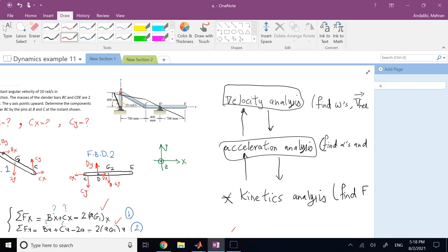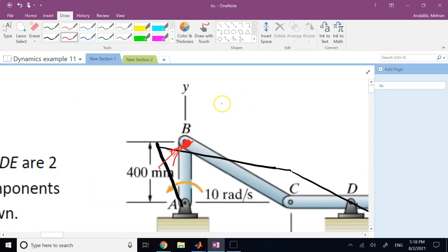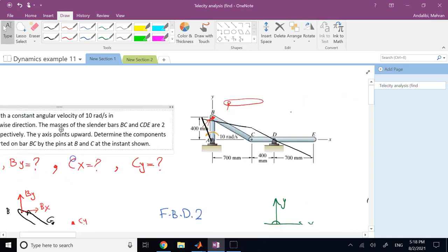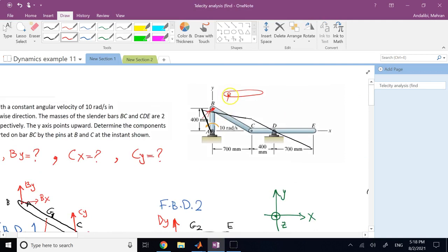And the other things are like the heat generated, there is a stress due to heat, there is lubrication. When you cut the member BC with that hole, there is another thing here called stress concentration and so on that you need to look at. So when you make the diameter of the pin bigger and bigger, you are going to add to the stress concentration inside member AB. So you cannot just choose whatever pin you want without looking at what's going to happen to member AB or BC or any other member that has the hole for this pin. You are making those weaker, right, by reducing the thickness at the hole and adding to stress concentration.